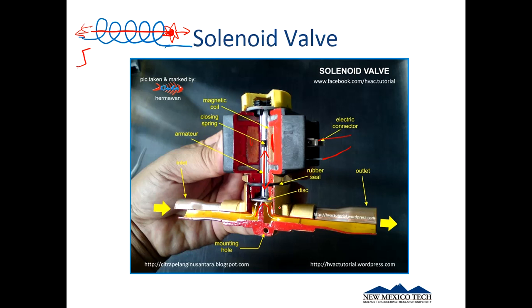And solenoid valves are really common. A lot of sprinkler valves are them. You'll use them in industry. It's a really common device because I can just change this. Typically, it's a 4 to 20 milliamp signal, and normally you have some other power source, and you're just using this as your control signal. But anyway, I basically vary between 4 and 20 milliamps, and that's like an industry standard. And I can change the position of this valve and control the fluid flow through there. So it's a really common device.